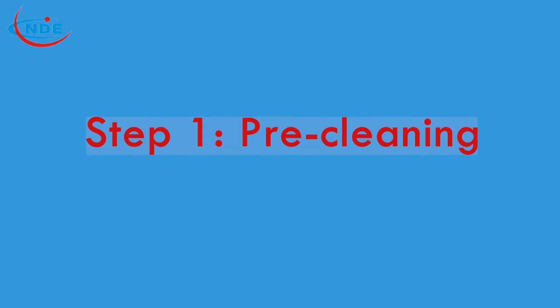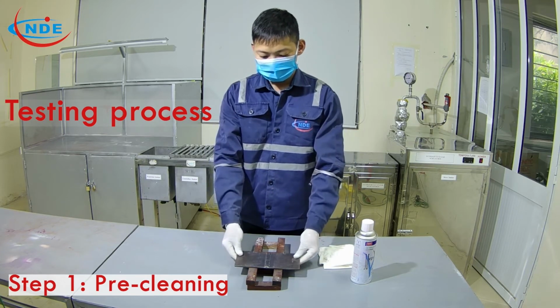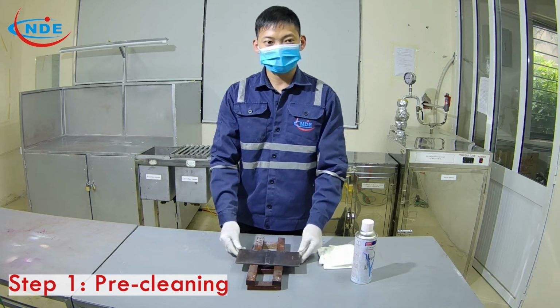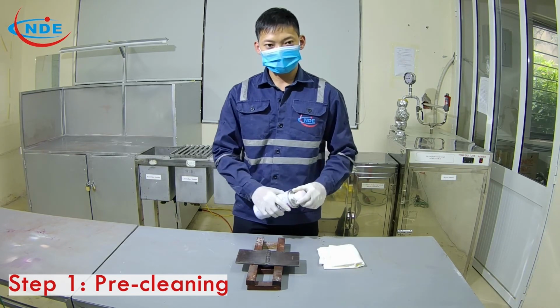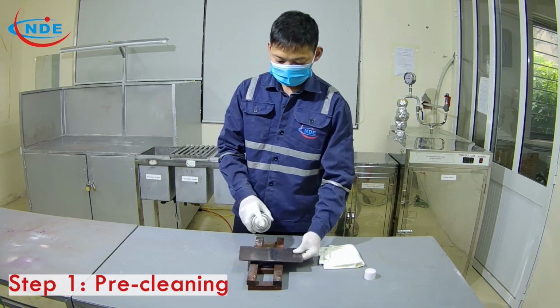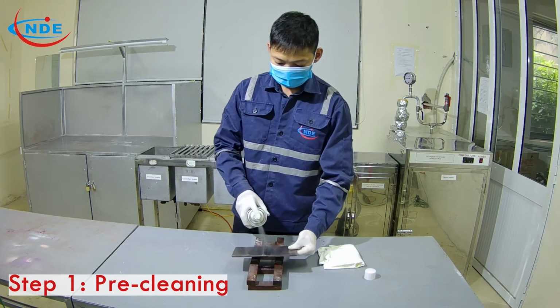The testing process includes 7 steps. Step 1. Pre-cleaning. Visually observe the testing object, and use a solvent spray bottle and clean rag to clean rust, grease, and stains on the surface of the testing object.